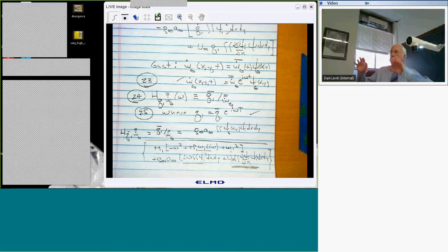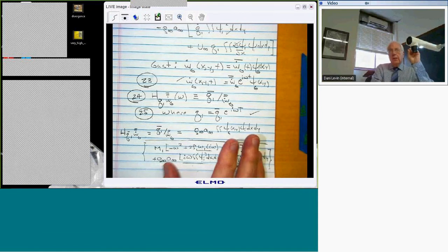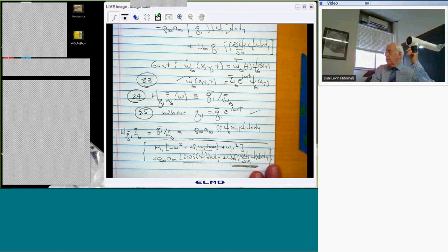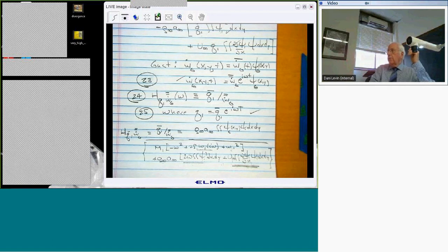Now, you might want to have more modes to get a more accurate answer, right? But the point is, qualitatively, and usually not too bad quantitatively, one mode analysis is okay for negative aerodynamic damping induced flutter. And often when people do turbomachinery flutter, they look at one mode at a time. They don't account for the fact that they may interact. Or you can produce, at least qualitatively, a divergence. But for flutter that's not due to loss of aerodynamic damping, and there is such flutter, the point of this homily is that you need more than one mode. You need at least two.